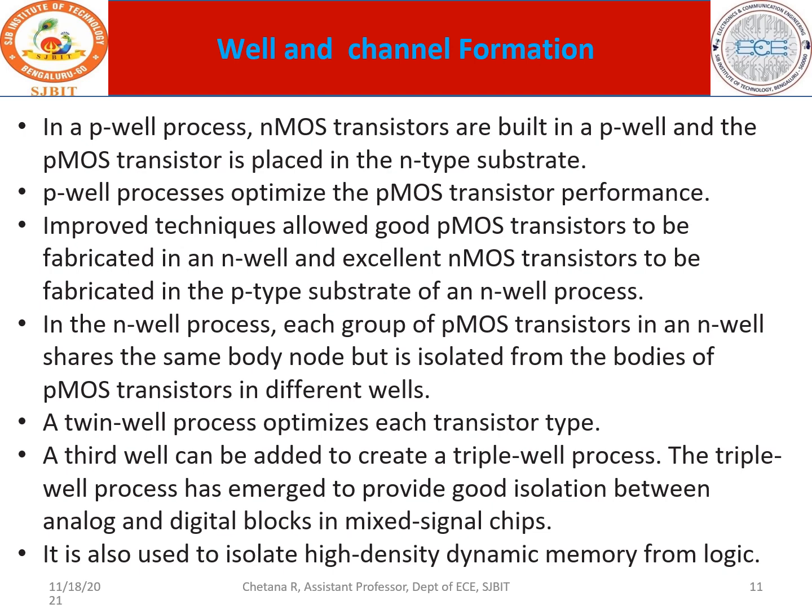Very well understood. Everything, all your diffusion, all your 3 terminals, source, drain and gate, are associated with one common substrate, either of NMOS or PMOS, because it is in a well structure. A well can be either P-type or N-type. Similarly, on the other well, they are respectively. So they are isolated from each other. They are in no way connected. So that is the beauty of the well structure.